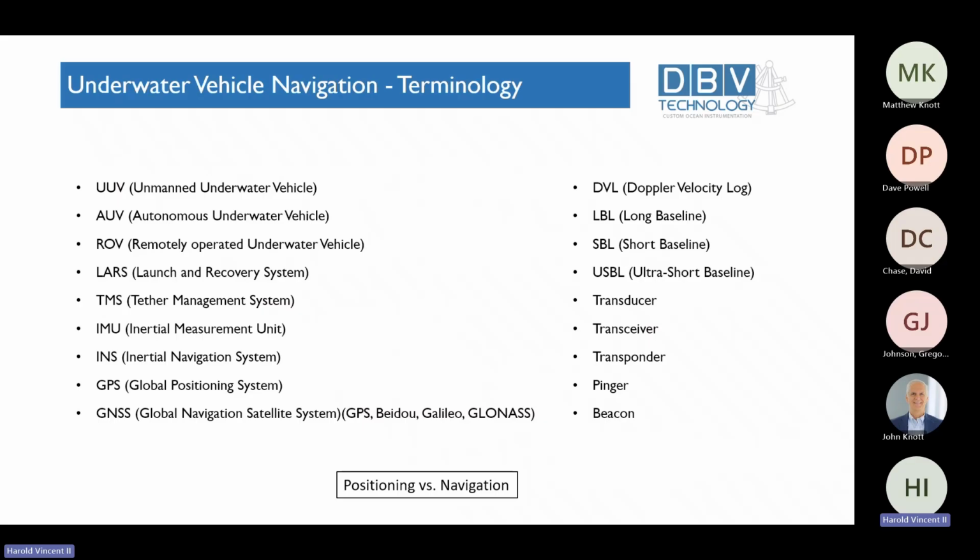A transponder, on the other hand, listens first, receives, and then transmits in response to a signal that it has received from the transceiver. The other difference between the two is there's sometimes a one-to-one correspondence. You could have a system functioning where you have one transceiver and one transponder, or you might have one transceiver and multiple transponders. So for example, in long baseline, there's one transceiver interrogating or downlinking or transmitting to a set of transponders that will reply or uplink back to a transceiver.